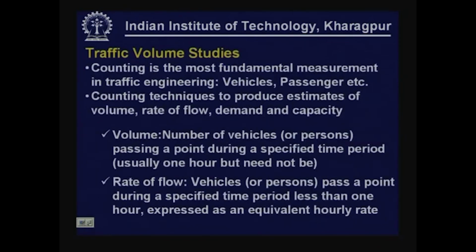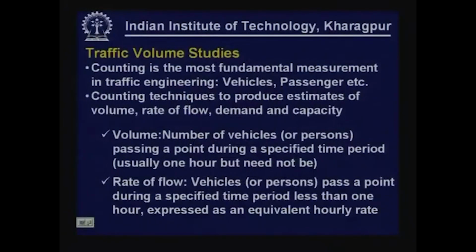Coming to traffic volume studies, counting is the most fundamental measurement in traffic engineering, counting of vehicles, counting of persons. So, for various reasons we are required to go for counting. It may be person, it may be vehicle, but counting is the elementary requirement: how many people, how many cars or how much vehicular traffic in general. So, counting techniques are used to produce estimates of traffic volume, rate of flow, demand and capacity.